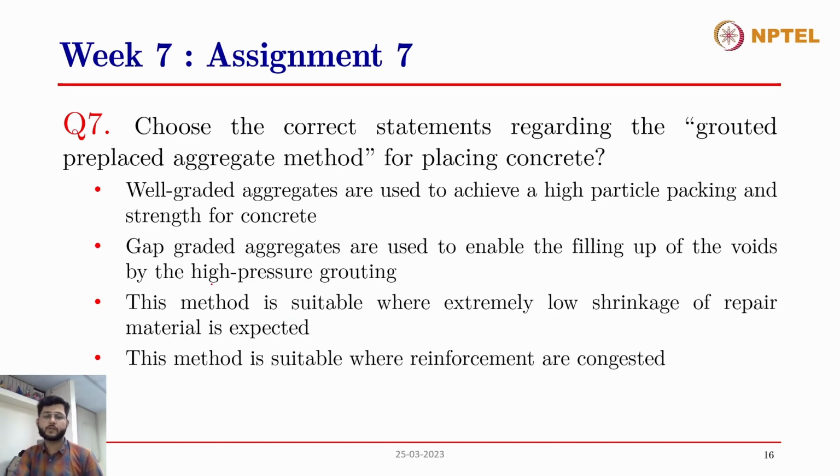The seventh question was, choose the correct statements regarding the grouted pre-placed aggregate method for placing concrete. The options are: well-graded aggregates are used to achieve a high particle packing and strength for concrete. Gap-graded aggregates are used to enable the filling up of the voids by high-pressure grouting. This method is suitable where extremely low shrinkage of repair material is expected. This method is suitable where reinforcement is congested. Which of these options are correct?